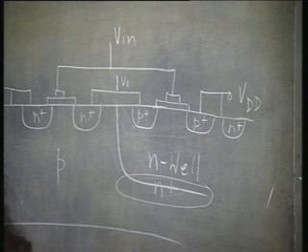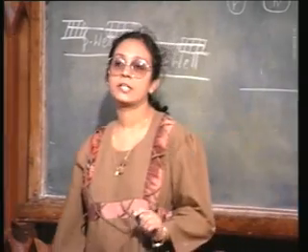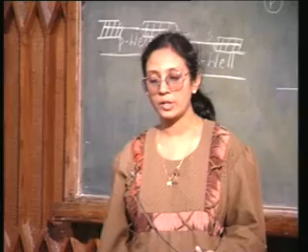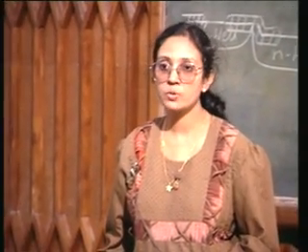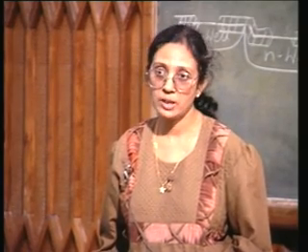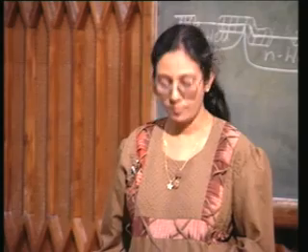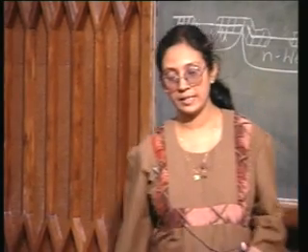So, this is called the retrograde structure, and the retrograde structure has now become quite popular in CMOS, in which case what we do is, aligned with each well, P well and N well, we have a P plus or an N plus buried layer.